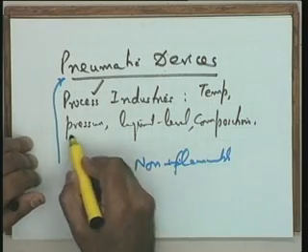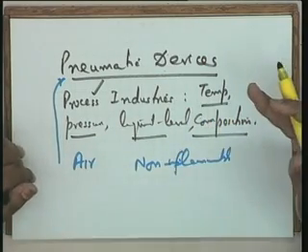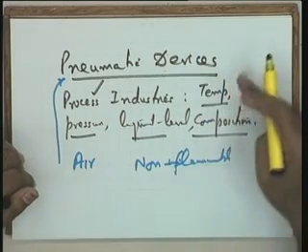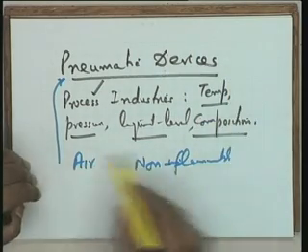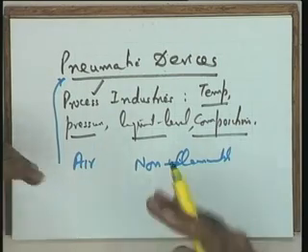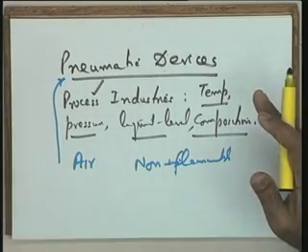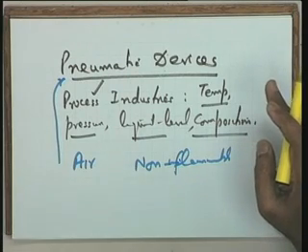So, it is because of this that the pneumatic devices are used primarily in these process control applications, because all these applications are slow in nature, and if these systems have got large time constants, in that particular case on a relative basis pneumatic devices can be effectively used. Your attention may please be needed here.